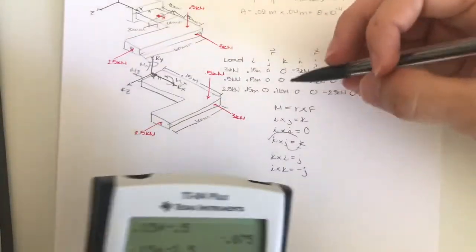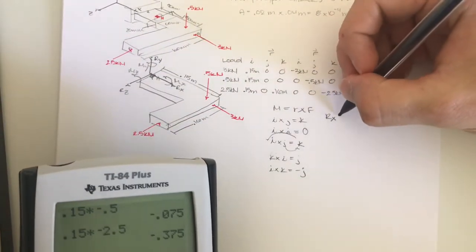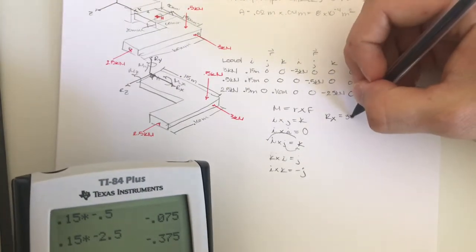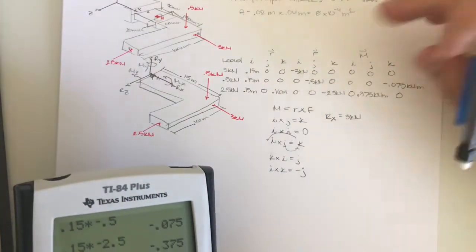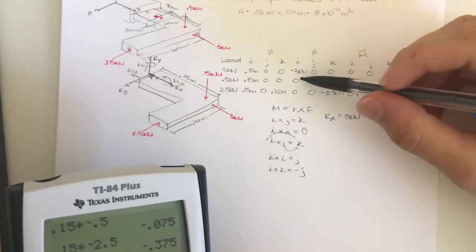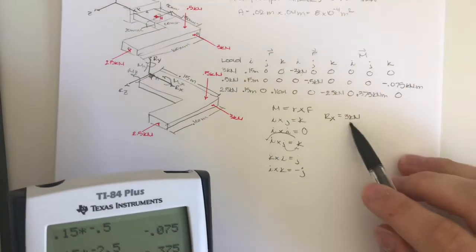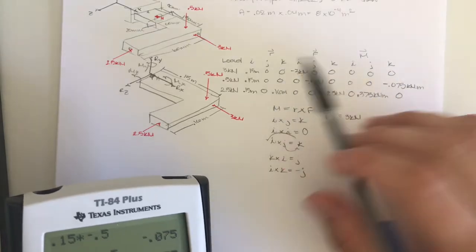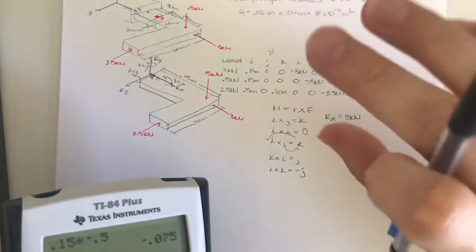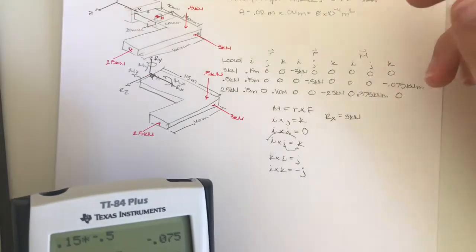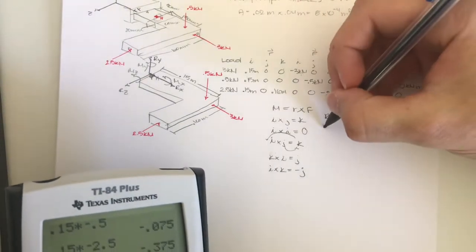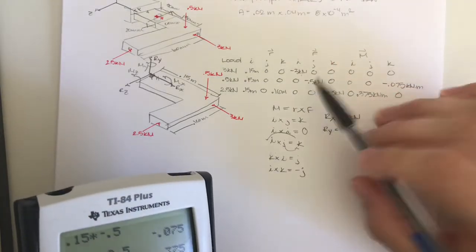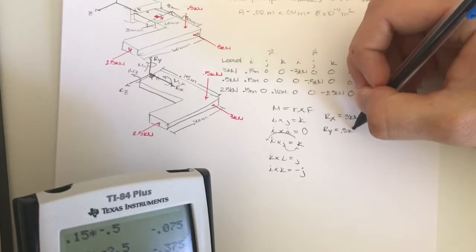Okay, so for the Rx, we are going to have 3 kilonewtons, and we are going to flip the sign of it. Since this is a negative originally, now it's going to be a positive, because the force and the position are what is actually happening, and the moment is the reaction, so we need to flip that sign to account for that. So Ry then equals 0.5 kilonewtons, flipping the sign since it's a negative here.